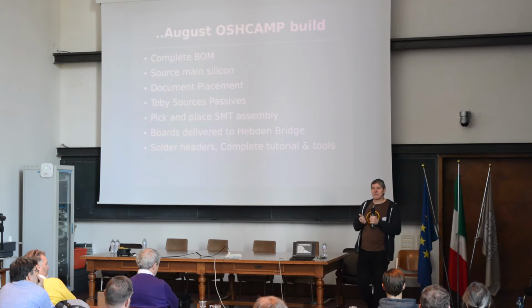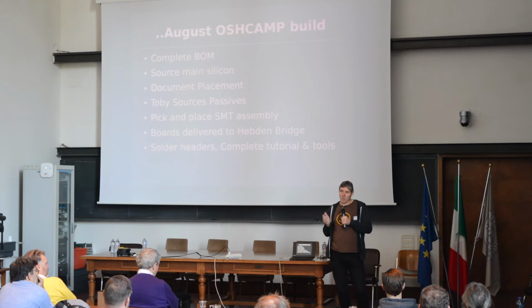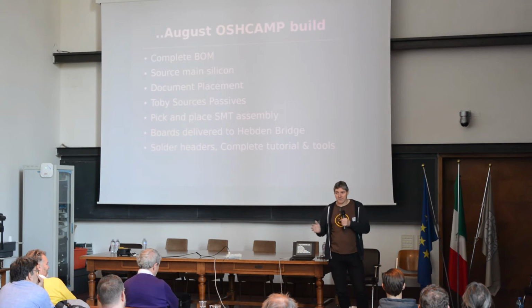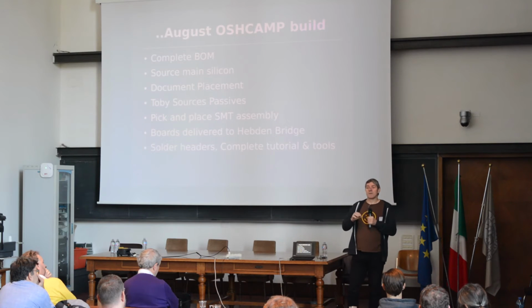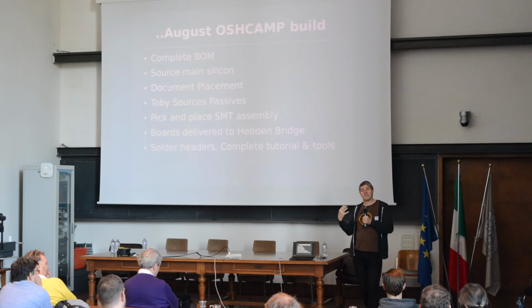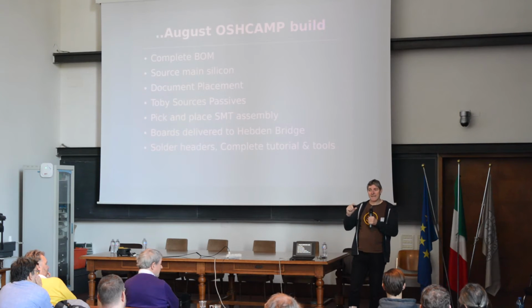We were also worried because we didn't know what equipment the people attending the workshop would have. And we were worried about, holy crap, how are we going to get this working on Windows? You know, at this point, we'd only worked with the Linux tools, etc. So we decided what we would do is we will actually use Raspberry Pis. Because Yosys, being the way it is, small, etc., it's actually very easy to get it installed on a Raspberry Pi. So you have the entire tool chain, including the ARM cross-compiler, and we have a little Raspbian image with all the bits and pieces we need.